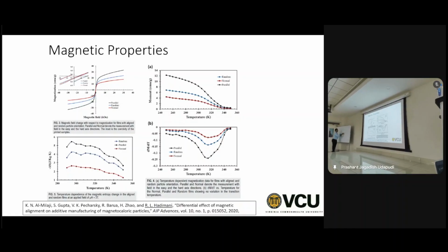A lot of the times, if you measure Young's modulus, electrical conductivity, thermal conductivity, or the magnetization, the long axis tends to be the easy axis, meaning you find a higher property, higher conductivity, higher magnetization or magnetic permeability, whereas the smallest axis will have lower, right?